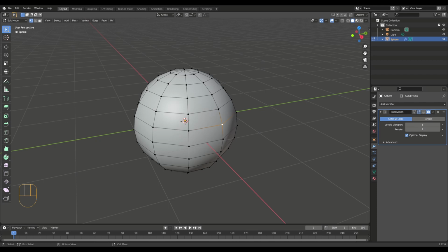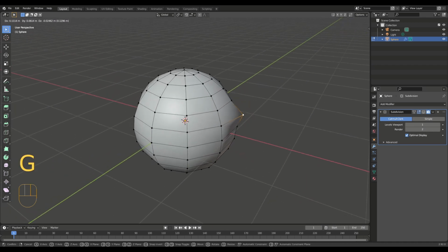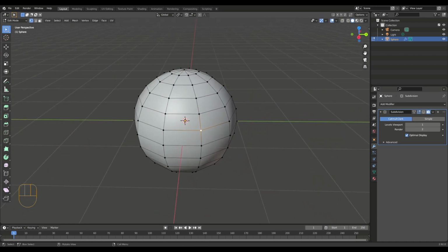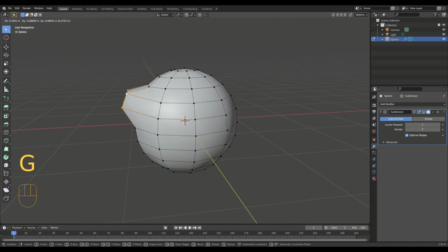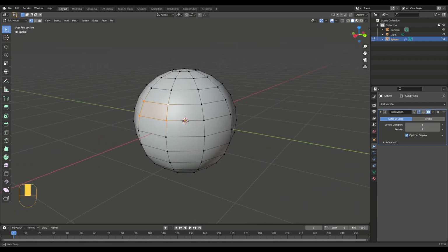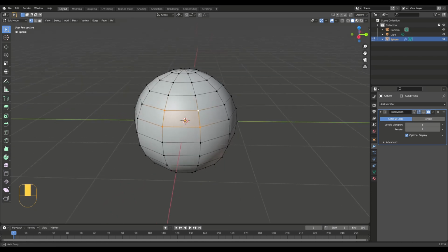You can select the vertices and move them with the same buttons that you used for shaping or moving the shape itself. So grabbing, resizing with the S key, or rotation with the R key. And these also apply with the directional limitations. In order to select multiple vertices, you have to hold down the Shift key and click on each one separately.